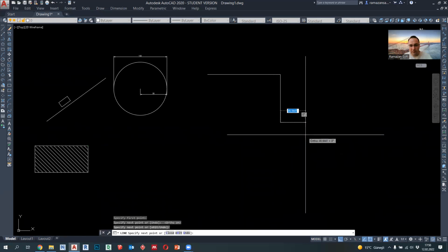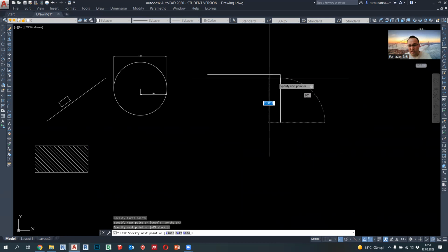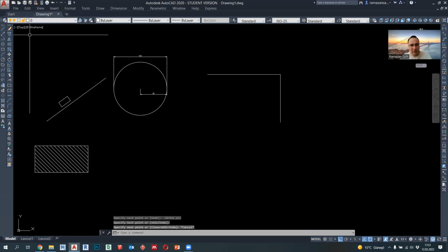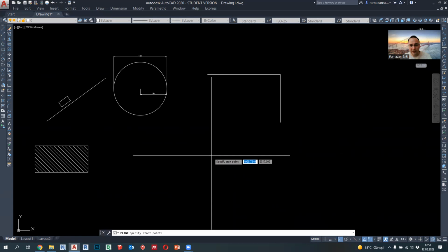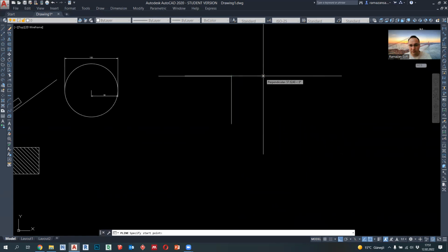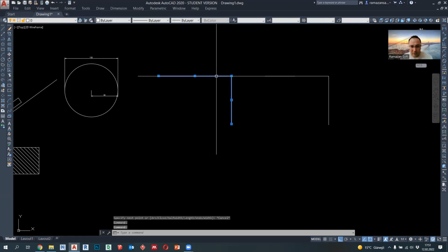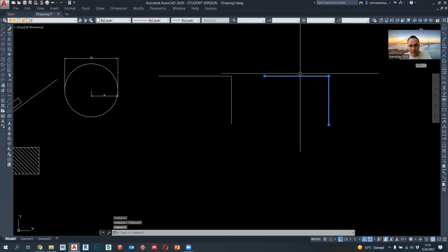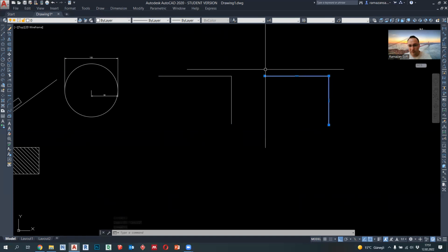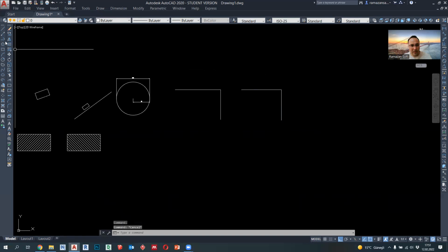When I create, for example, these two intersecting chain lines by using line commands, and let's make the same process by using polyline. When I click the first example, you see there are two separate lines. However, when I click the second example, you see the lines are connected, or the lines are unique, actually. It helps you for moving, rotating, and making any process when we use the polyline command.